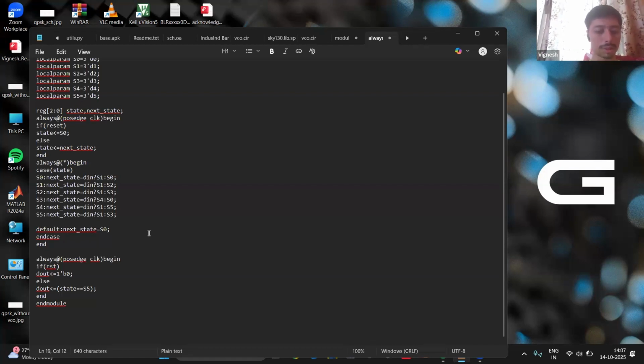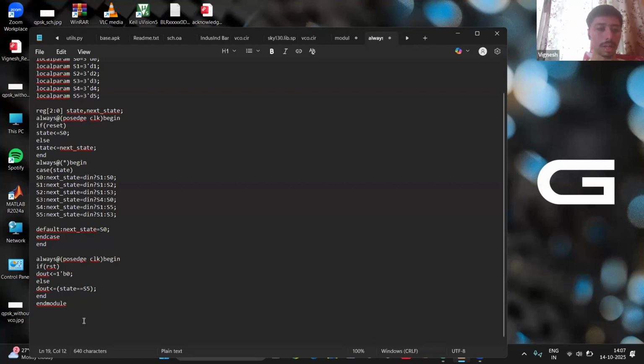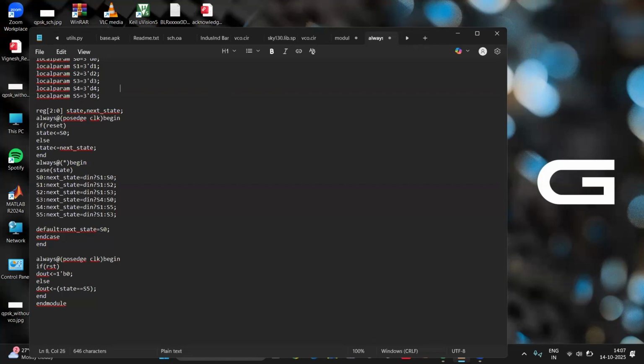So a latch is basically something which does not have any clock, and it remains on till the enable is one. A flip flop is the one whose output is dependent only on the rise and fall edge of the clock. So when you mean the combinational inference, how do I say? I'll just write one sample code, let me know if this is correct. Yes, yes, you can.